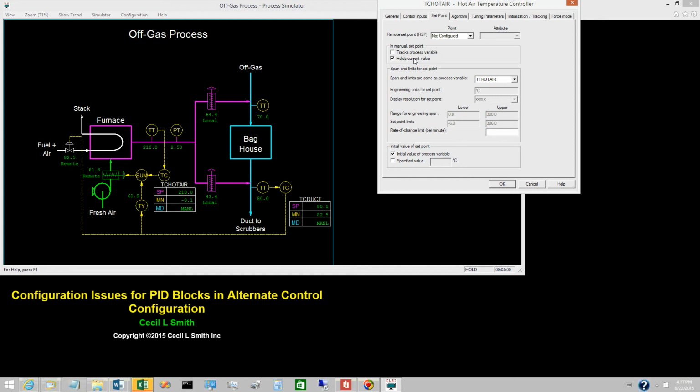The bumpless transfer calculations will initialize the PID equation such that control commences from the last output value in manual. But if the PV is different from the set point, the controller will start driving the output up or down depending on the sign of the control error. Commissioning the ratio control configuration that uses the characterization function is the subject of the next video.